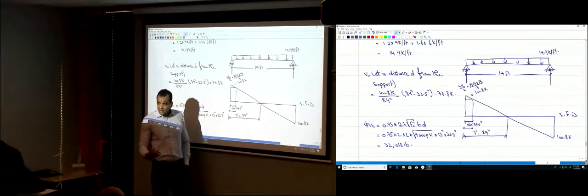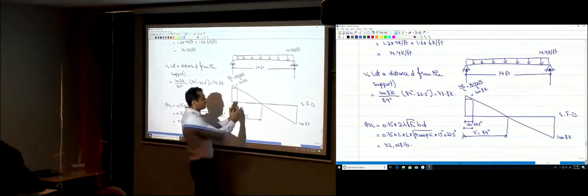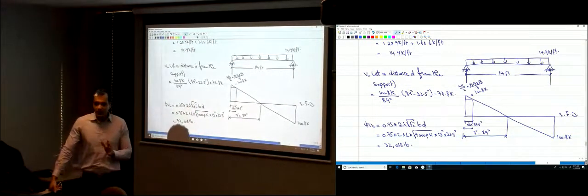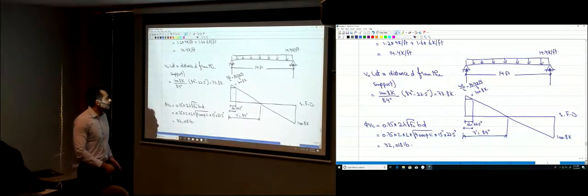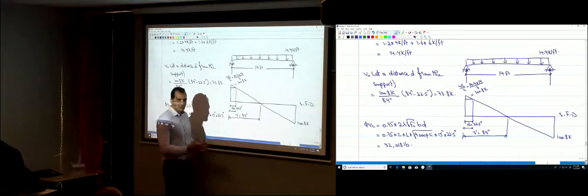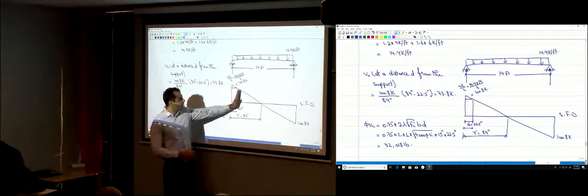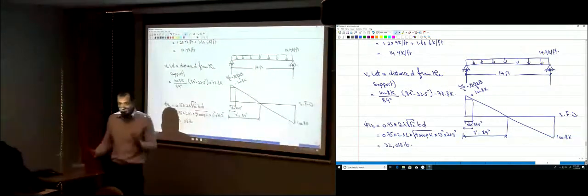What we're going to do as a practical practice is, at the beginning we need 5 inches, and then I'm going to change from 5 inches to some other spacing that I need, and then maybe change it again. So maybe just 3 parts: 5 inches, then another value, and then a third value. Right now, definitely you can choose a different value, but I have 5 inches spacing here, and at some point I will increase that spacing from 5 to 9 inches, to save some money.